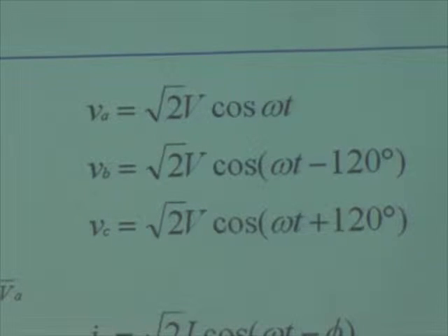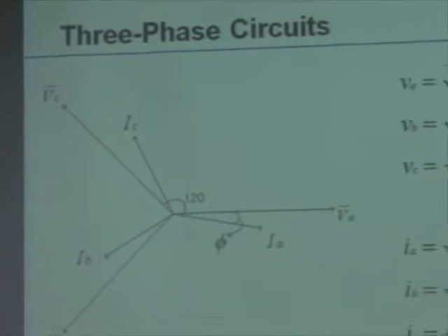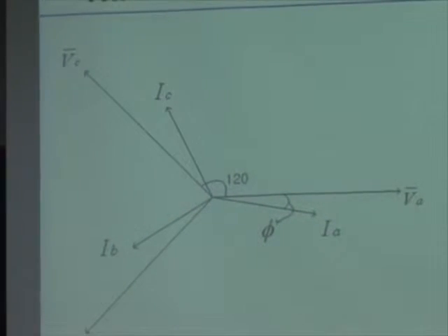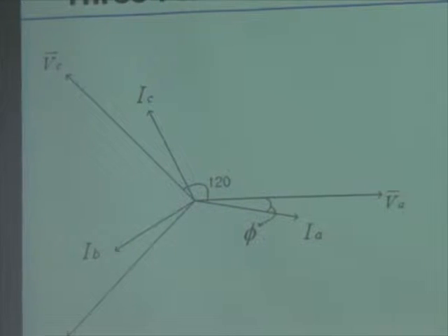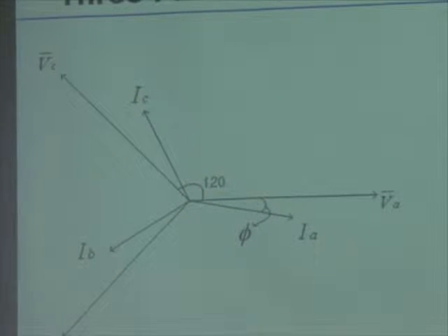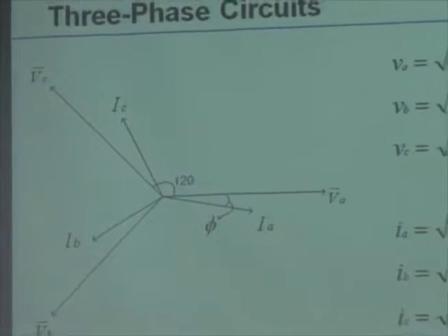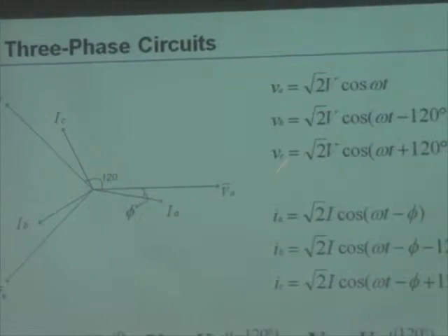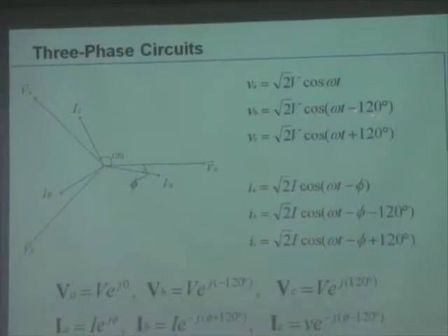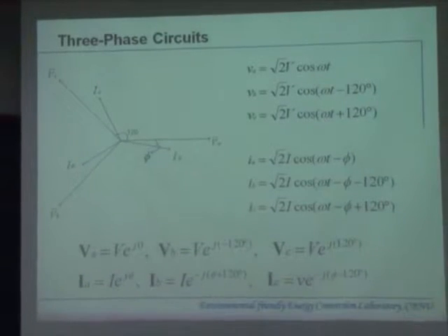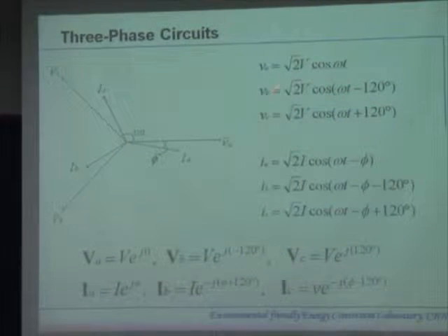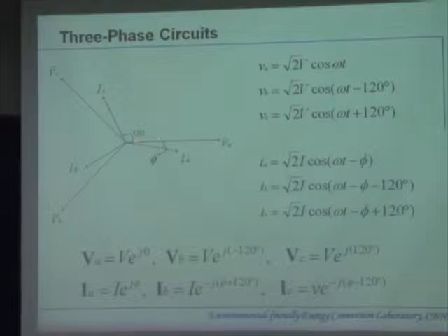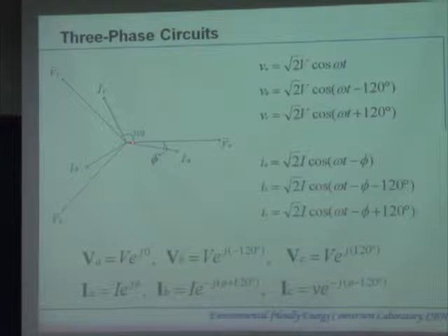Here, what is this? This is a phasor diagram. This is a time domain. We change to the phasor domain. What is the phasor? I explained last lecture that phasor is a complex mapping having the amplitude the same as the RMS and the angle the same as the phase. So once we describe this phasor of this three-phase time system, we can have VA and VB and VC.